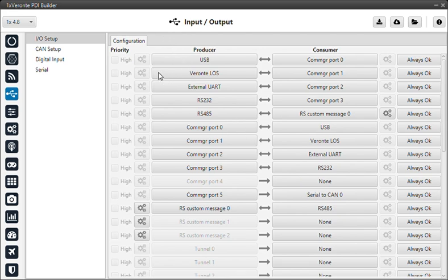block program for something else, for the control logic, for the guidance, for also custom block programs that can be used in the automations, and so on. So I'm just obtaining this data through this. This can be done for the movement actuators, but also for sensors themselves. We can have a magnetometer connected to RS485, and we want just to save this value and use it as an external sensor.